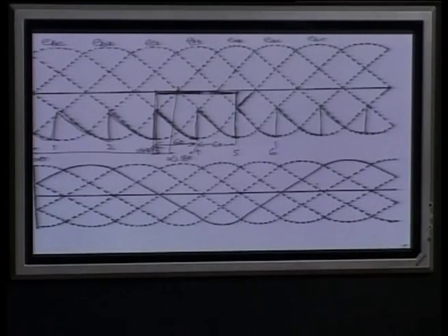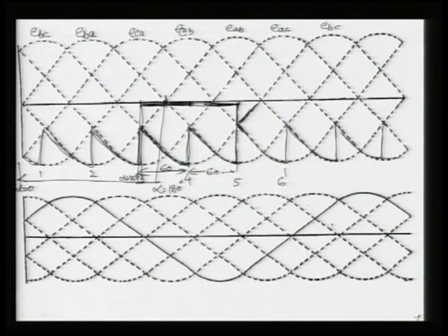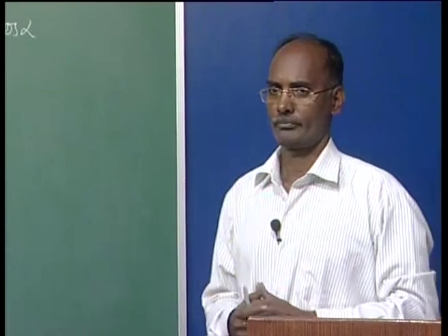So, it will follow even up to the 6th valve firing, and it will be going up to here. Valve 6 is fired and still it will continue, and here valve 1 is going to be fired. So, it will be going up to this portion, this is the valve voltage I am drawing, the thicker line. Now, 1 is fired, then A is coming on the cathode of valve 3 and B is also there.